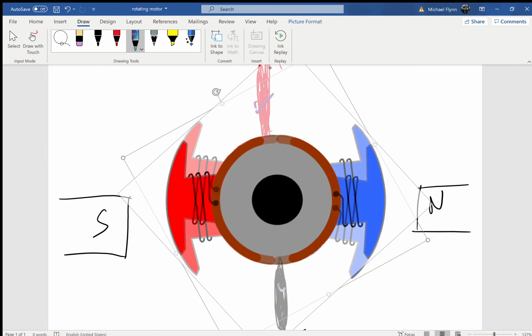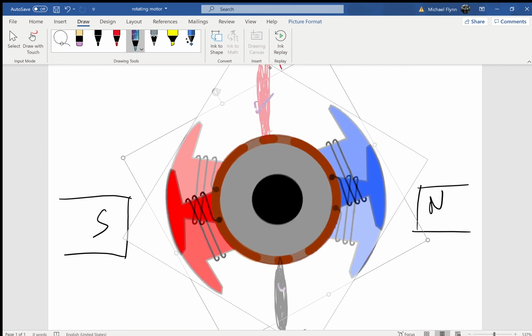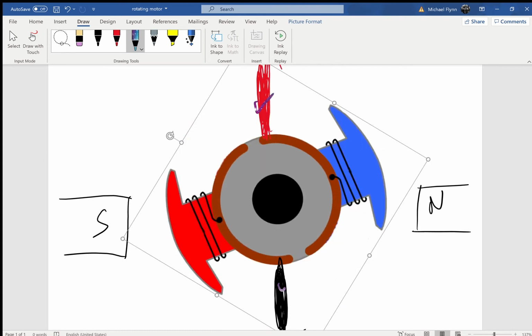Now the red brush is passing over the gap, and then here in this position, they have now switched which half of the split ring that they're touching, right? And so now what's happening, if I trace the current like I did before, the current is going down here like this now on the blue side. Okay, it comes down here like this as before, exits this way, okay, and it goes out that way.